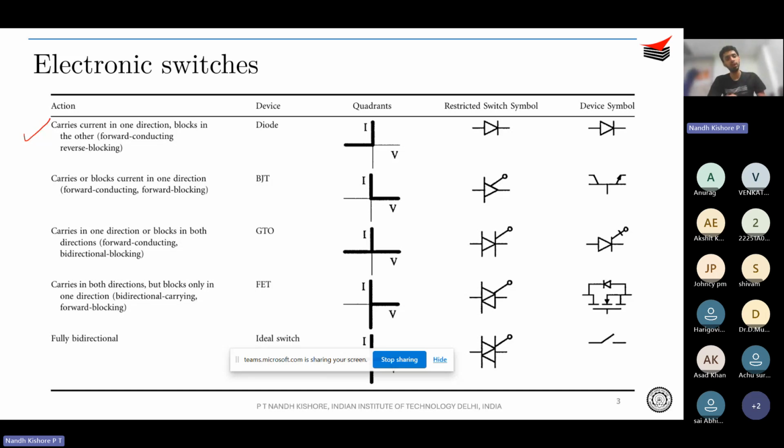So in this week you learned about BJTs, right? So you of course know that a BJT can carry the collector current, right? And there would of course be a drop VCE if you take an NPN BJT, right? So it can block positive voltage as well, because unless you supply the base current required for the device to turn on, the device will not turn on, right?